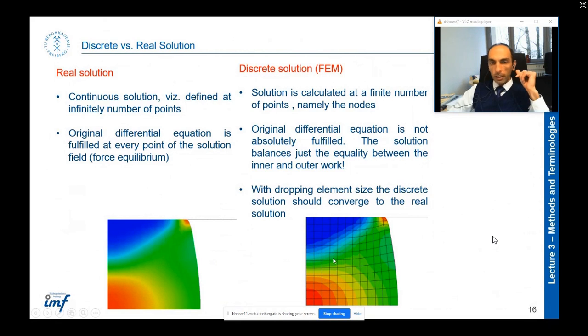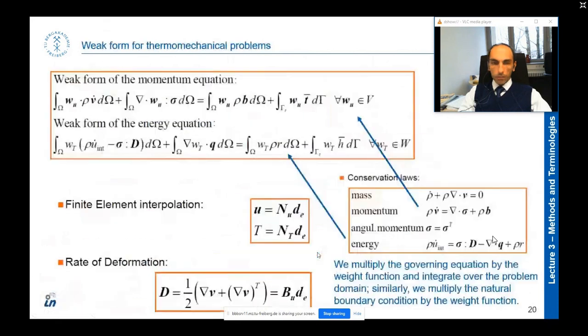Then we use a kind of interpolation function. Again, I will explain about it more later. We use the interpolation functions to connect all the nodes and the results obtained on the nodes together, and obtain the results for all over your body, your workpiece.